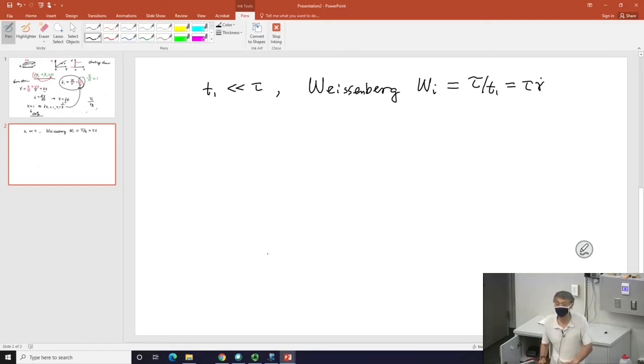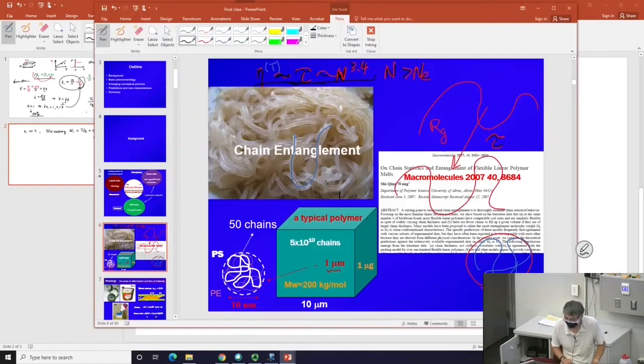Of course, we know that when this number is very large, something is being deformed fast. But concretely, we are talking about fast in the sense that within tau, I will move, where the Weissenberg number is 100, meaning I will move 100 H to the right. And think about this object that has a particular tau involved for this complicated object.